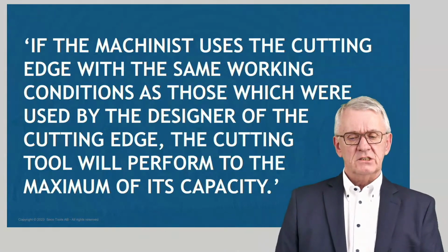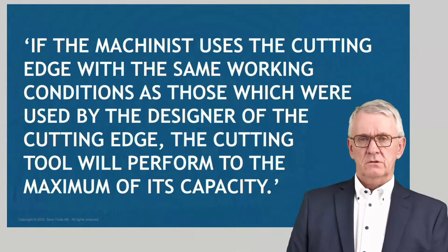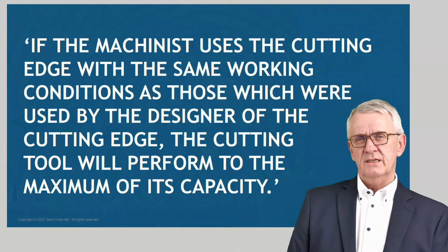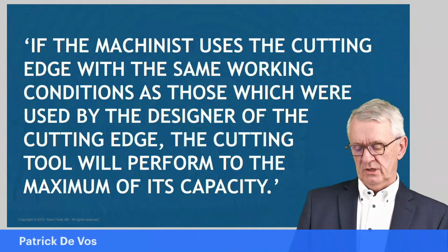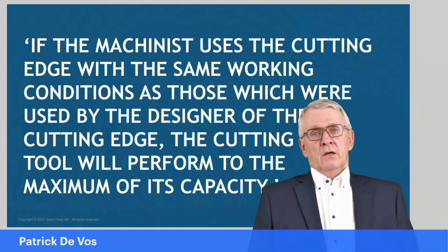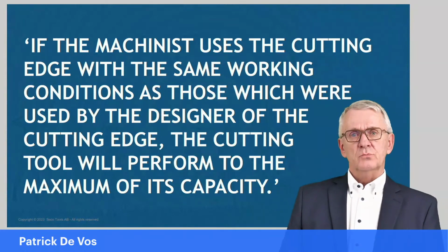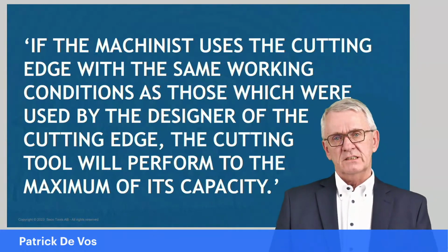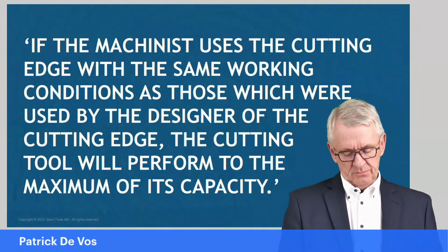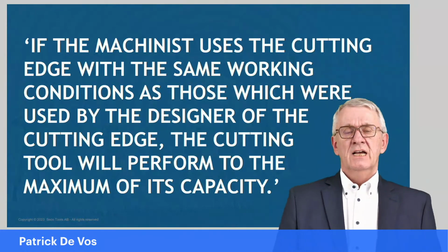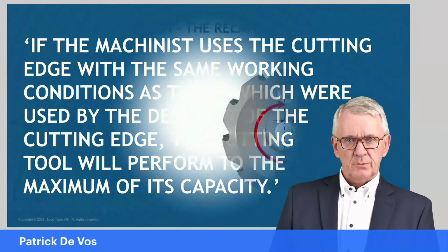And this is really what it's about. How to proceed, that I exploit the possibilities which are built in a cutting edge as much as possible. And that is possible, but then we have to take as guidance the criteria used by the designer of a milling cutter, and that is what we have been doing, talking about chip thicknesses, feed, average chip thicknesses, equivalent chip thickness, and in the end, dynamic milling principles.